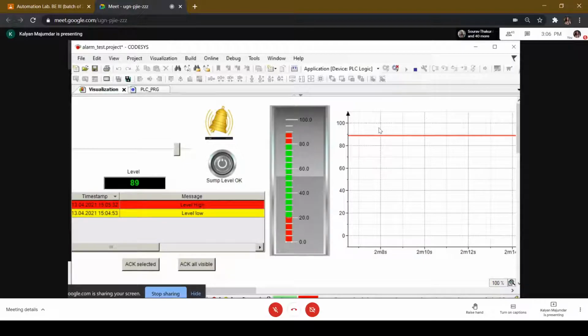Here, of course, the information seems to be redundant. I've said the same thing both in the bar graph and in the trace. Probably it appears that why should I say the same thing twice? But the reason is that in practice, in one page you simply have such bar graphs indicating levels multiple times, and the trend page is a completely different page where you just have a huge plot showing a huge number of variables.